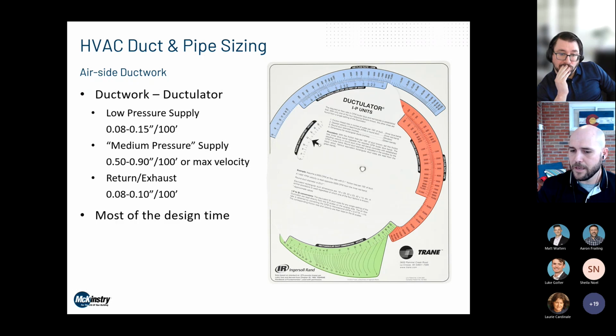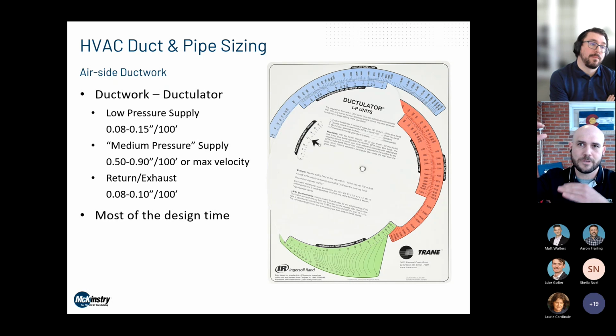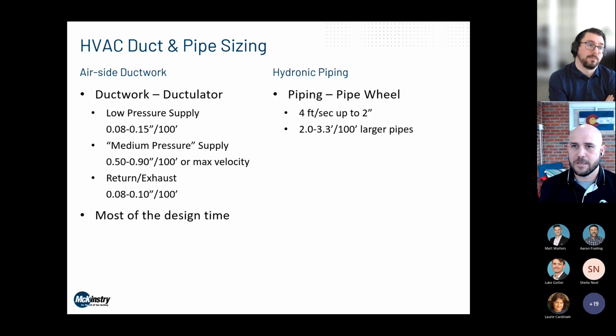And there's something similar. It's worth noting, this is where design engineers spend most of their time, in routing ductwork and coordinating it with structural elements and ceiling heights. You're arranging branch takeoffs and duct crossings and trying to make sure that it all can fit between the bottom of the structure and whatever the ceiling is, and coordinating all different kinds of things. So you can do the calculations, you can size the plant based on your block loads, and then this is where 70% of your time actually is spent.